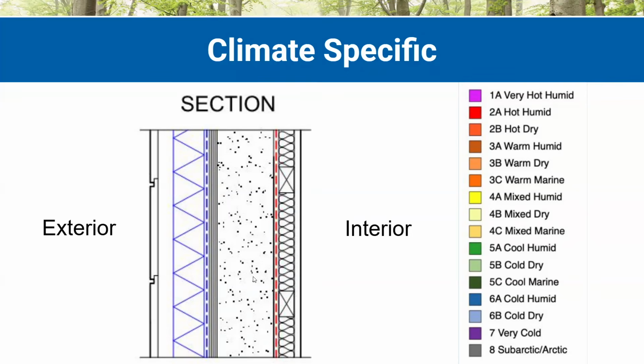We're probably using a 2x6 cavity that we're filling with a mineral wool bat or unfaced fiberglass bat or a blown in cellulose, and really prioritizing a good Intello membrane. And then for climate zones 5 and up, again, we're really prioritizing this Intello membrane and we're just making all of our insulation layers thicker. We're trying to increase the vapor permeability on the exterior.